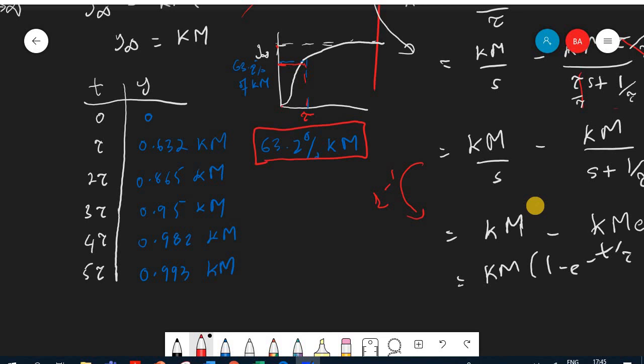So for example, I have a tank. And within that tank, I open this Fi from 20 to 30%, and because of that, my tank level changed from 3 to 3.2. Okay, so what is the change? It changed from 3 to 3.2, so the change is 0.2. If I multiply 63.2% by 0.2, I can find what? I can find the value of tau. And that's the beauty of it.